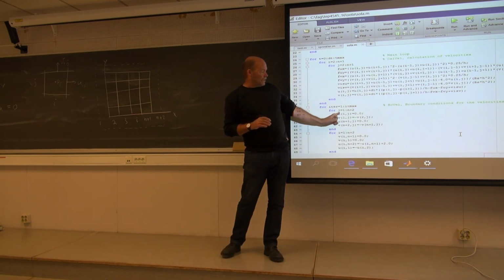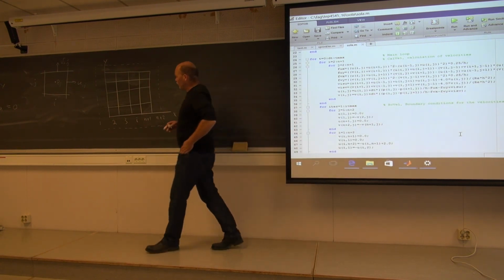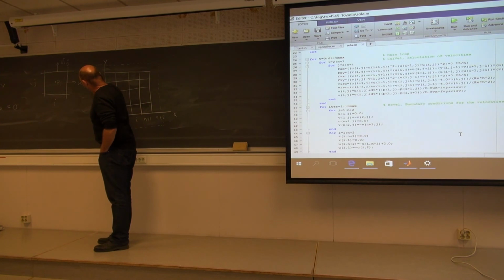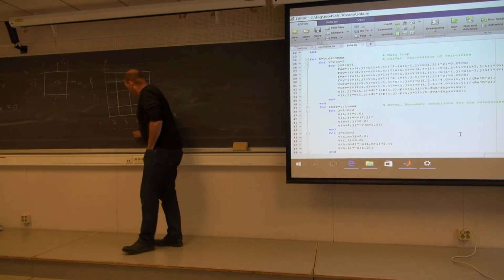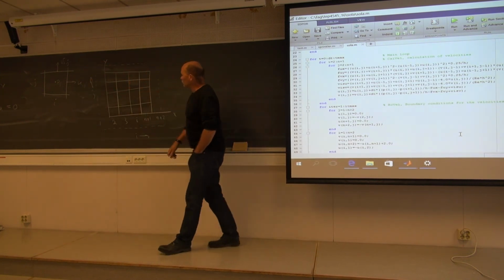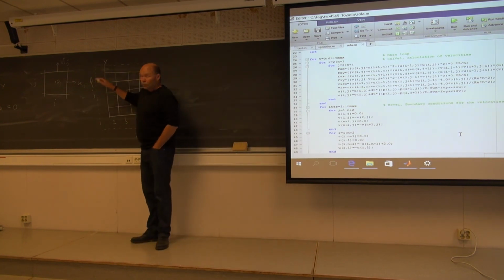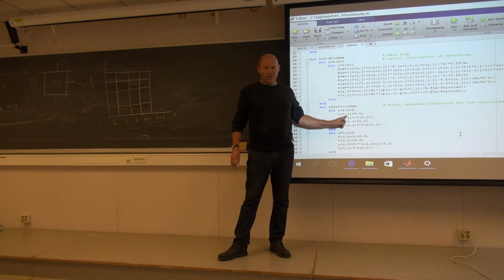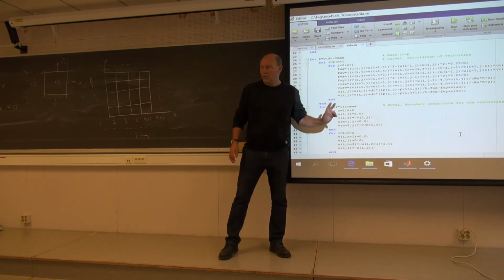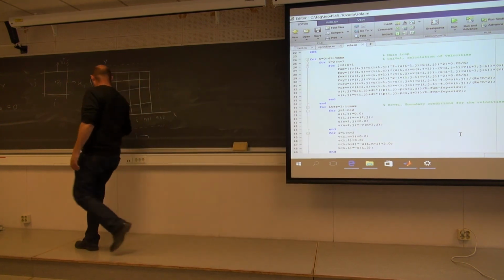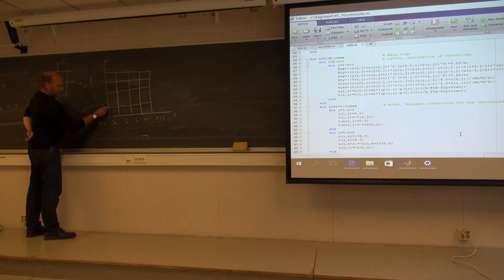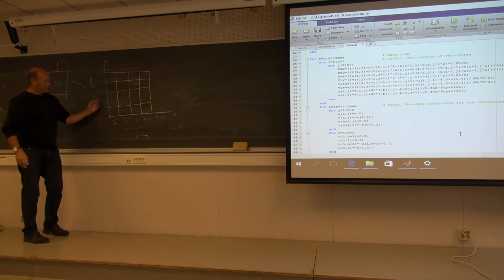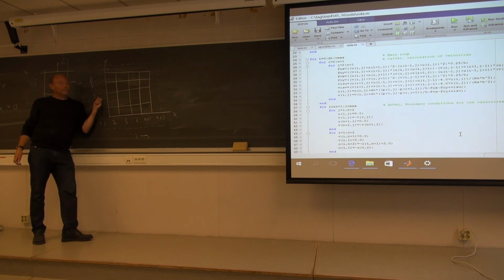For all j's, from 1 to n plus 2. J, that is up here, that's the y direction. I, that is the x direction. So for all these, we have written here, u number 1, comma j is 0. U number 1, okay. Cell number 1, they are these fictitious cells here inside the wall. These are cell number 1.